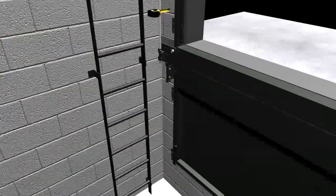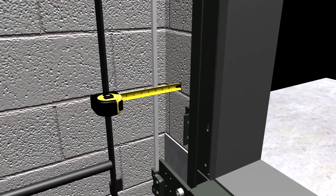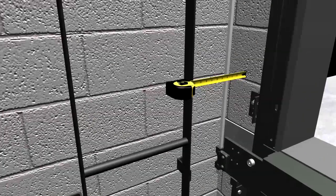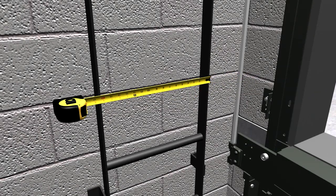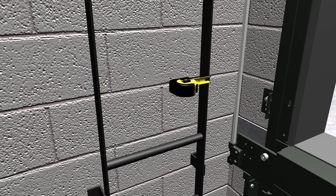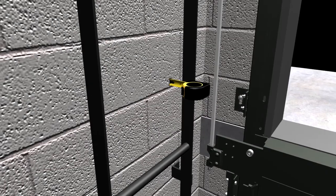Look for any obstructions, such as pit ladders, and document their location. For traction elevators, note the location of the elevator counterweight and measure the distance from the front shaft wall.